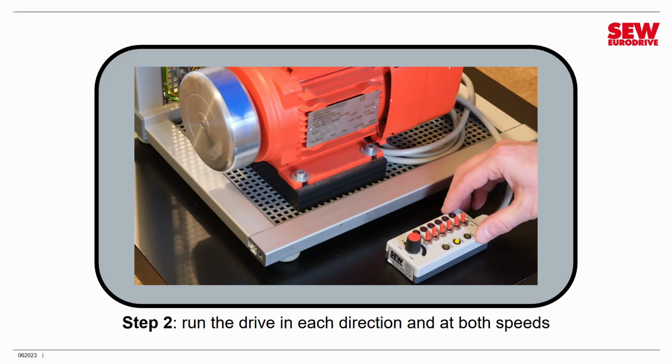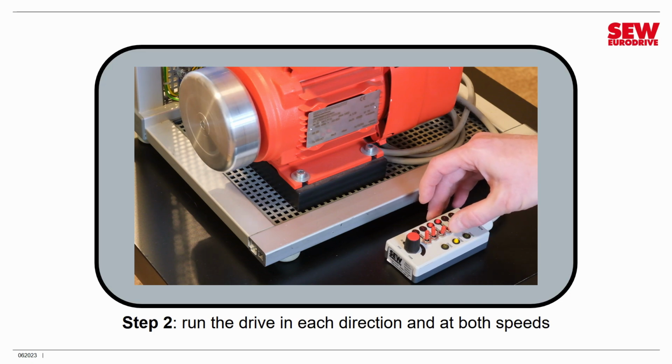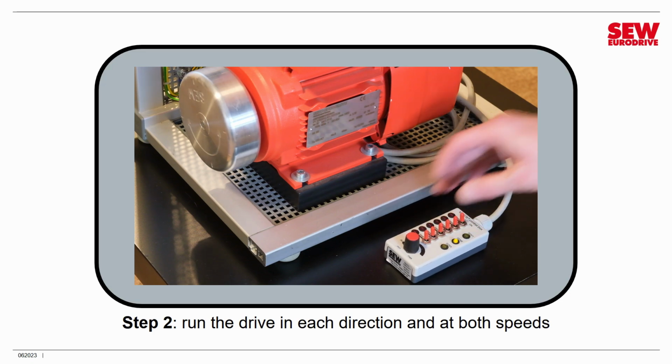Now we'll switch to the F2 speed, which is 300 RPM, and you can see we're definitely running at a much lower speed. Runs fine in clockwise, and runs fine in counterclockwise. So it looks like everything is working correctly here. MOVIMOT is easy.